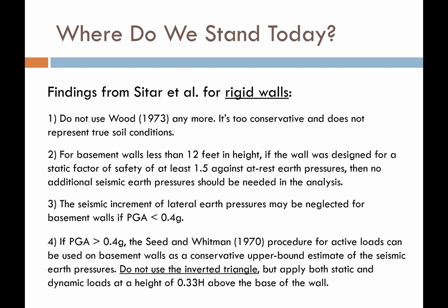For rigid walls, here's what Sitar and his students recommended. Get rid of the Wood 1973 recommendations. He said they're way too conservative and they do not represent true soil conditions and what has been observed in the field over decades. So just don't use Wood 1973 anymore.